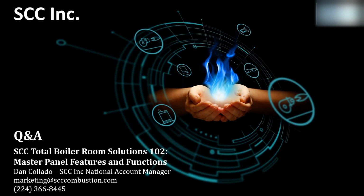The other option you have is to actually use the 4 digital outputs that we showed in the input-output config screen. And you could assign 1 digital output to each RTD, creating a dedicated high stack temperature alarm or dedicated interlock function. And this would give you the ability to do basically a high stack temperature shutdown.